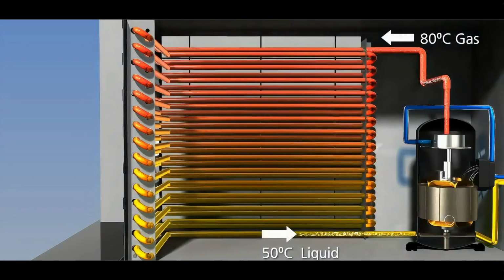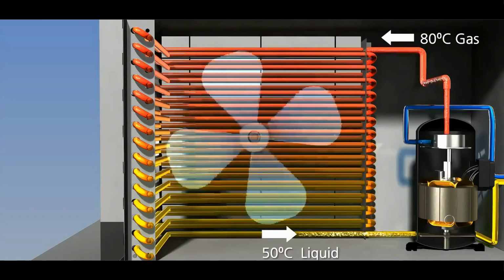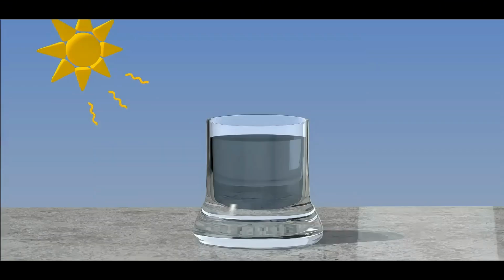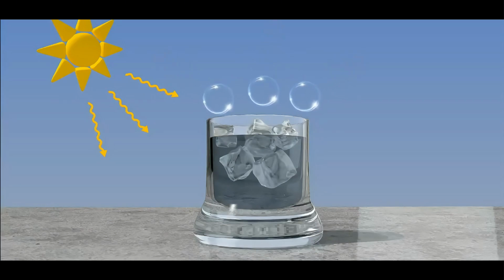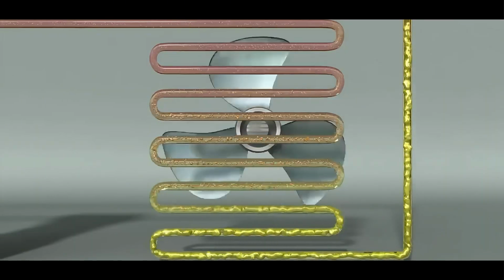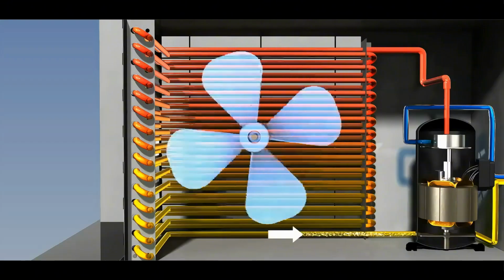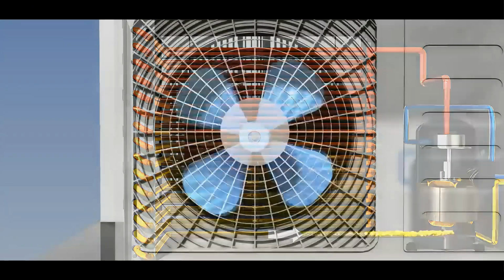The temperature of refrigerant passed through the compressor is above 80 Celsius, which is in a hot gas state. This refrigerant passes through a condenser and is cooled down slowly with chilled air from fans. When liquid evaporates, it absorbs heat and becomes gas. As it transforms into gas, its kinetic energy becomes stronger. When the gas loses heat, its kinetic energy becomes weaker and it becomes liquid. In other words, chilled gas becomes liquid. A refrigerant in gas state of high temperature loses heat as it passes through a condenser. As such, it becomes condensed and at the exit, it turns into liquid almost.